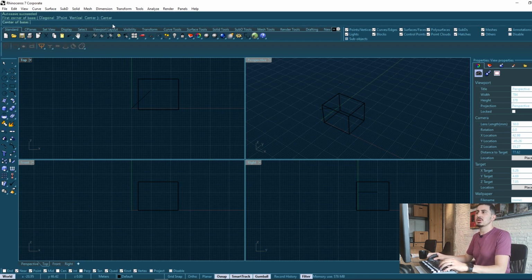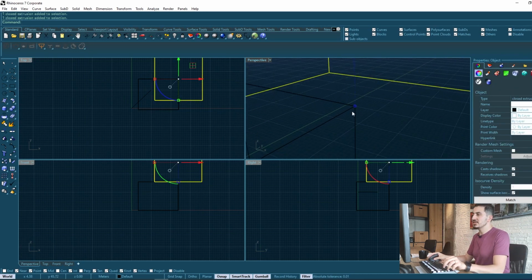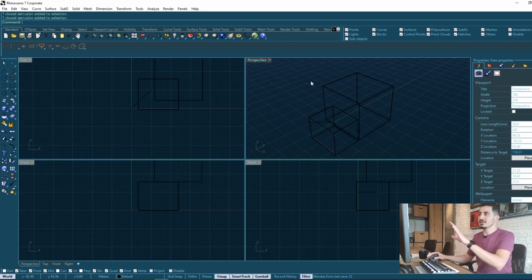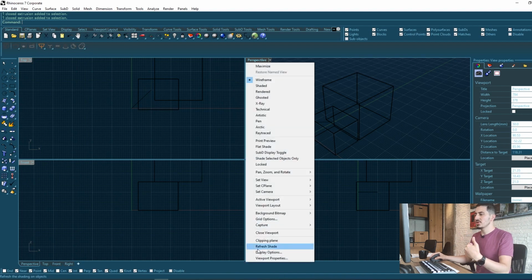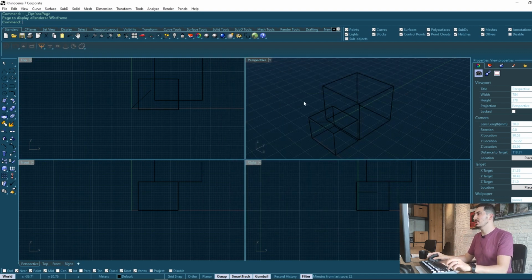So you can use all of these commands with different attributes to each one of them. So for example, I want to use the center, and I can choose this as my center. Now I know that it created the box using the center of the base of this box. I believe that the interface of my program is different from the one that you're using, the colors are different, but it's just because I played with the display options and changed the view colors, but that's not very important for now.